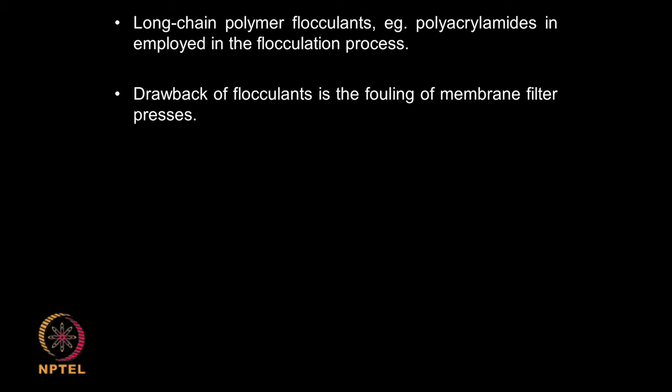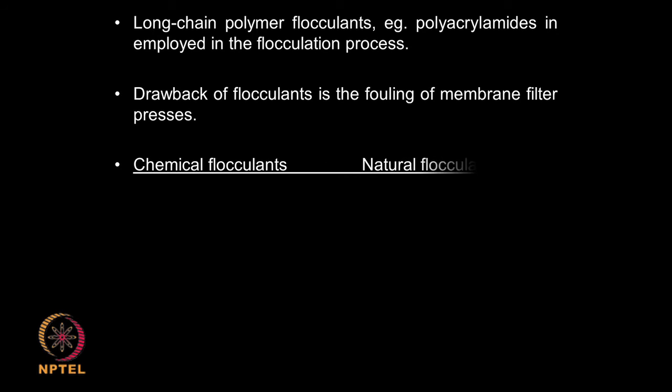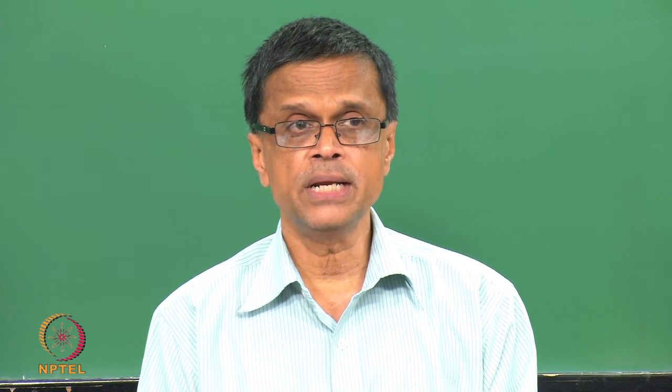So, the problem with these flocculants is the fouling, they can foul your membrane, number 1. Number 2, they become impurity. If you are interested in the solid particles, then they are impurities that will be present with the solid particle. So, then it becomes very difficult for you to separate them out. If liquid is your desired product, then there is no problem, but still flocculants can sort of foul your membrane.